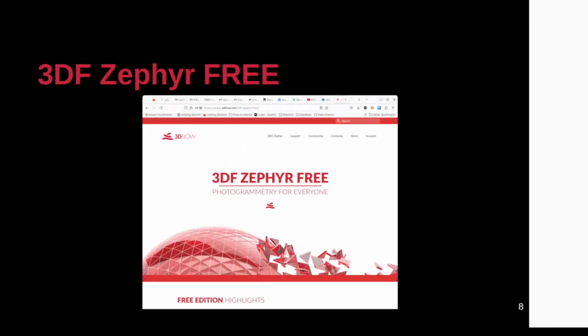3DF Zephyr has a camera calibration feature that is very simple to use. Simply load several images of the calibration target in slightly different angles and let the app perform the calculations of the calibration coefficients. The results can be exported to files to minimize transcription errors of long strings of floating point numbers.